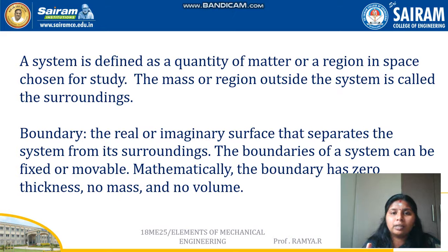The boundary may be a real surface, or we can imagine that within this area we are doing the heat concentration. Apart from this, other things are surroundings. So a boundary is an imaginary or real surface that separates the system from its surroundings. The boundaries of a system can be fixed or movable. Mathematically, a boundary has zero thickness, no mass, no volume.